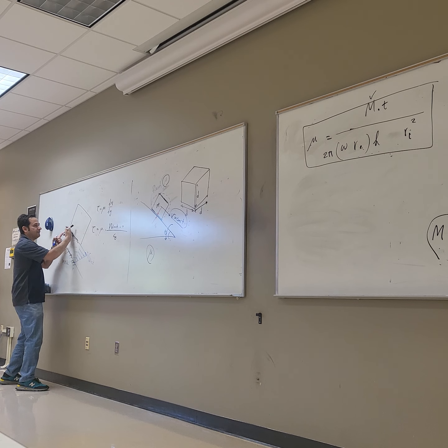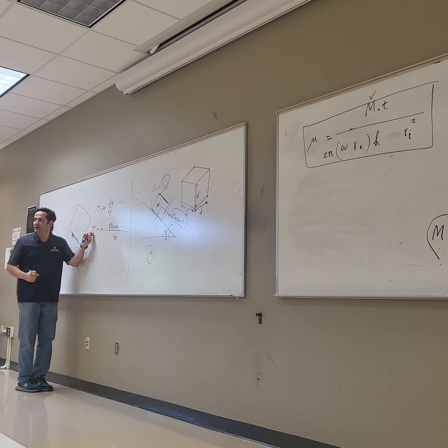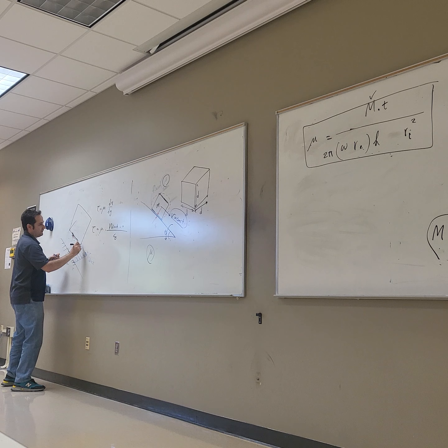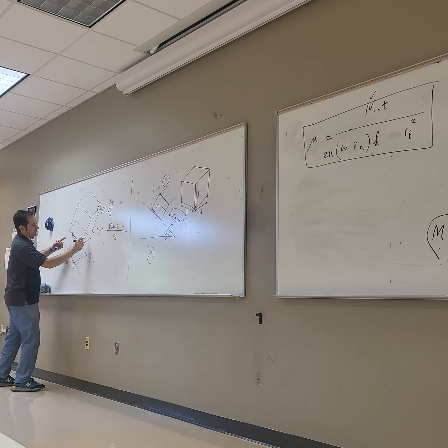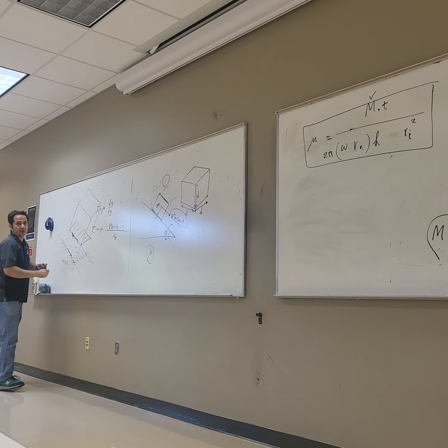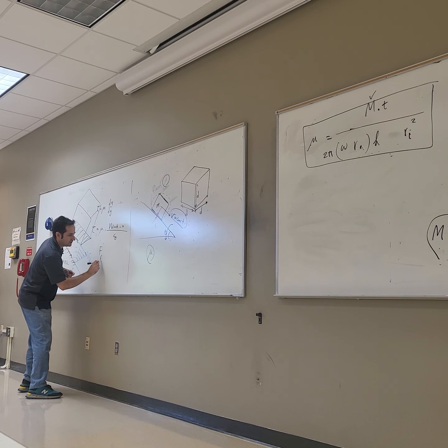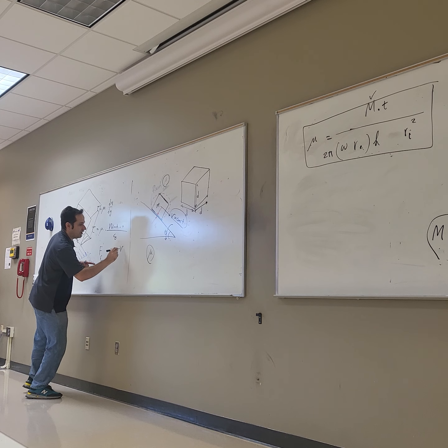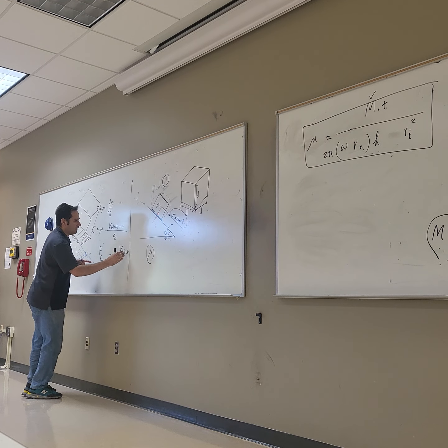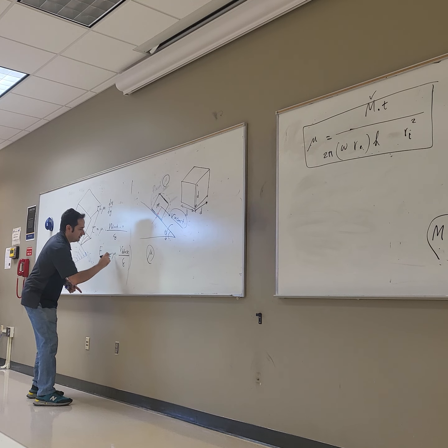But it's just shear stress. In order to get the resultant frictional force on the block, what should I multiply this by? The surface area of this block. You see this block is like that. What's the surface area of that? D squared. So you multiply that, and the frictional force coming from the lubricating fluid is mu V block divided by delta times D squared.